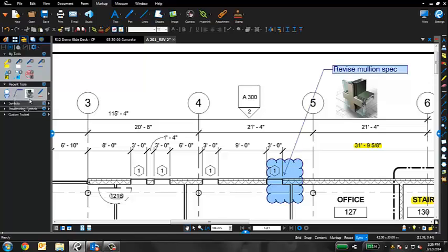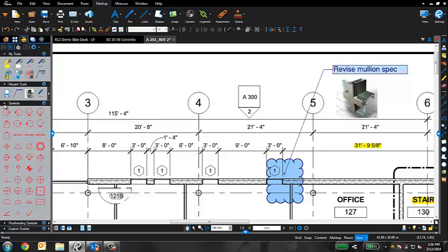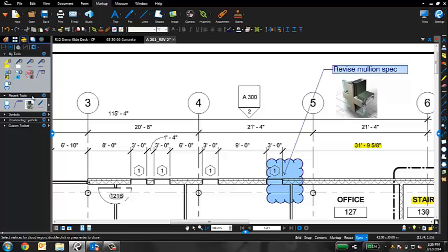Recent tools is like a cache in your internet browser. It's going to erase all the recent tools that have been used after every review session. But no problem, you can go ahead and click and drag those tools right into My Tools or any other tool set that you've selected and save them forever, and they'll never move. So in recent tools, as you can see, I have my cloud right here, which I can go ahead and save for later use, so I don't need to change the colors on that.